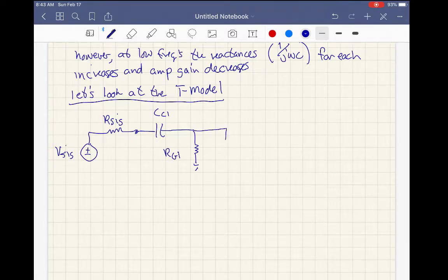RG2 is, I guess we could say, still at ground. Okay. We can model a dependent current source here, if I can draw it right. We can say ID, little d, is equal to I little s. Stick another resistor here. This is the 1 over the transconductance, gm. And you remember gm is ID over VGS.